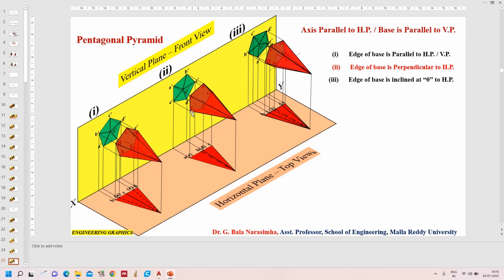The edge EO is invisible, but it lies exactly beneath the AO. So here this is the hidden line and this is the visible line. According to the priority of the lines, the first priority we will give to the visible line. So no need to draw the hidden line here. And coming to the center line, DO is hidden. So that's why we can draw hidden.